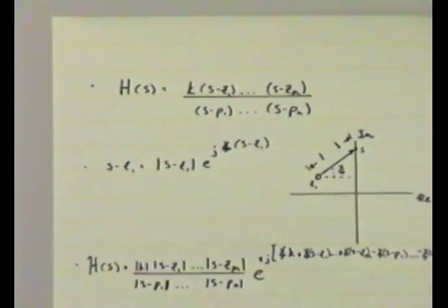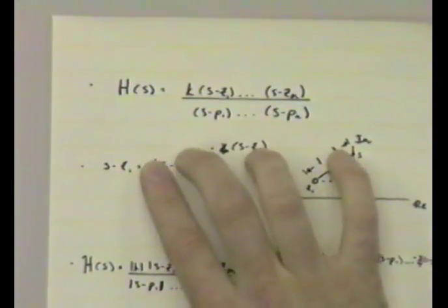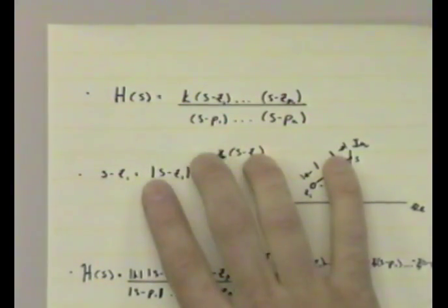We have to factor these polynomials, right? And we learned early on that to factor anything other than second order is really quite a mess, right, for the third order. And in fact, above that, we really can't do it. So we're cheating here in the sense that in order to put the transfer function in this form, most often we'll have to rely on some piece of software to give us the pole and zero locations.